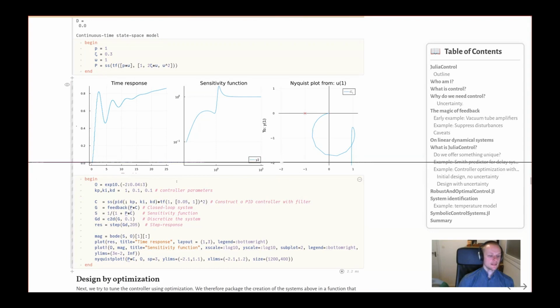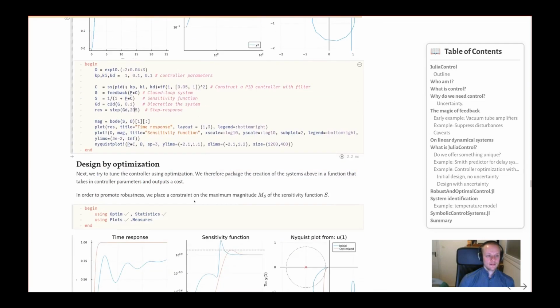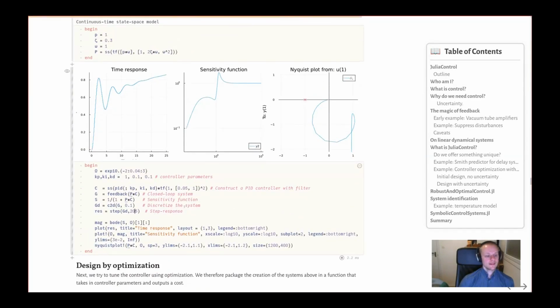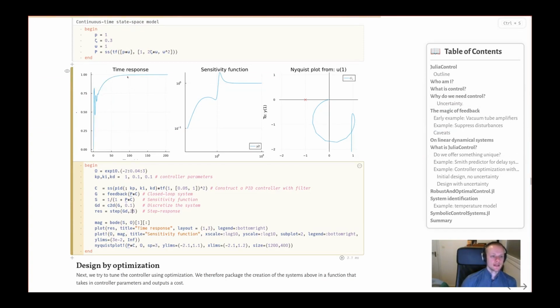we will see it will slowly work its way up to 1. And if we simulate even further, hopefully. What did I do here now? It's thinking about it. Anyway, it would eventually reach 1, but it's going very slowly. Yeah, here we see it reached 1 after a while. But we see that it has a very horrible response. It oscillates quite a lot, and then it's quite slow in reaching 1. So this is a very poorly tuned control system so far.